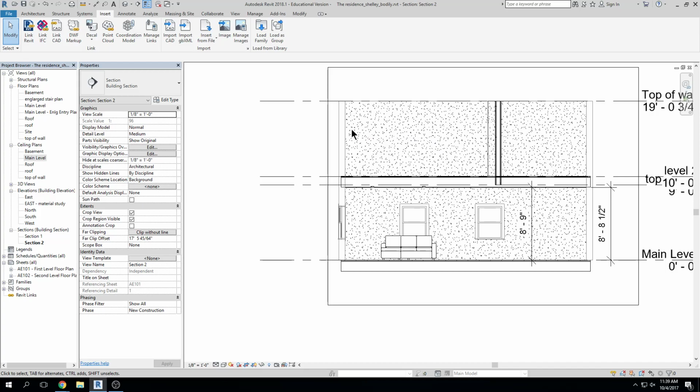A soffitted area is essentially where you have to drop your framing down, so you have a wood structure or a steel stud structure to support a ceiling that pops down a certain distance from your field ceiling, and then has lights or whatever in it. It could accommodate structure or ductwork, or maybe it's just aesthetic, acoustics, whatever.